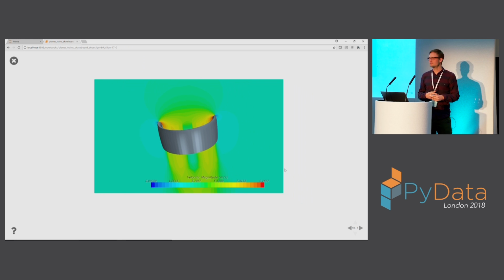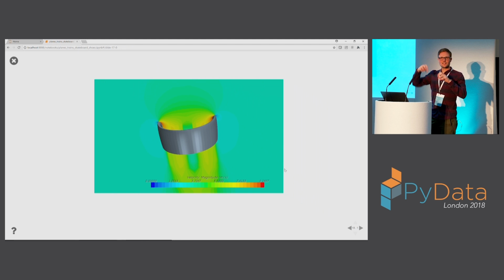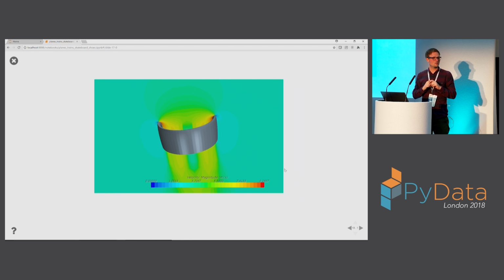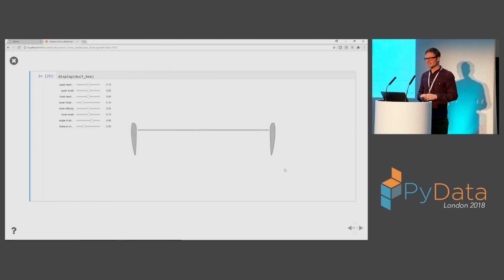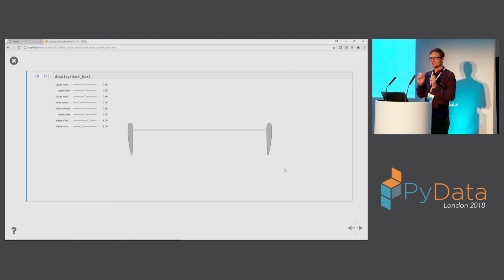And the idea is that you're adding this thing which should theoretically mean that you need more thrust to keep this drone up in the air. But if you design it carefully, you can actually generate thrust from the ducting itself. And the way you do that is you pull the air through it, and if you can get a nice region of negative pressure on the front leading edge, you're causing a component of lift as well. So that's what we're really going for here. But it's quite a challenging problem in the sense that the geometry is so subtle, it has a big impact on what the performance of the actual ducting would do.